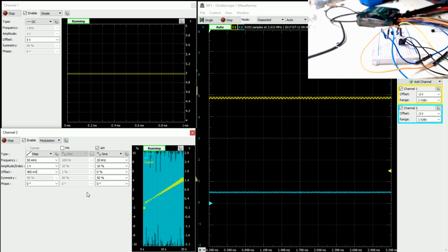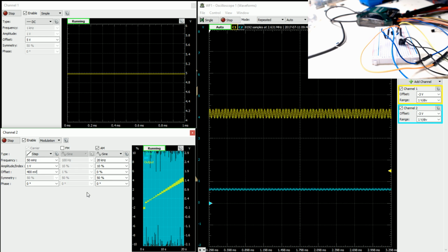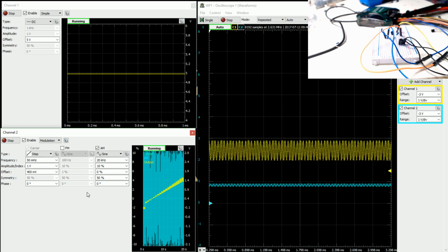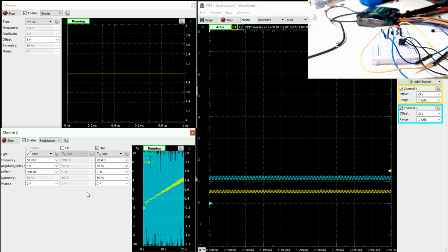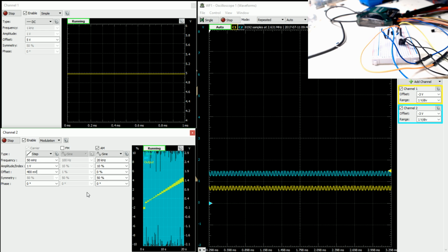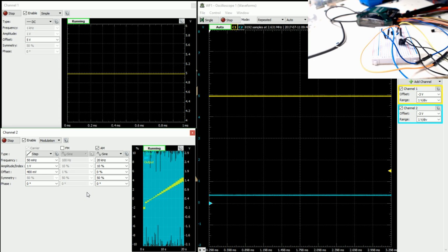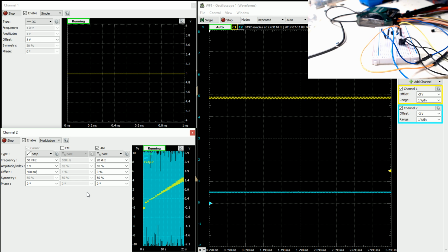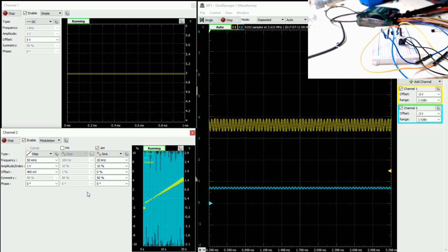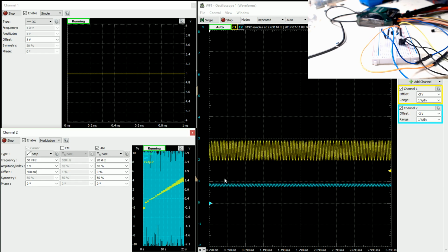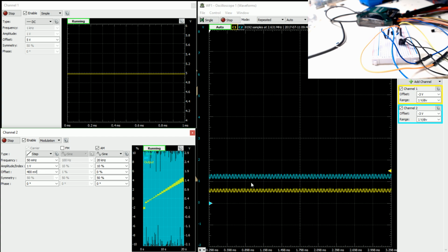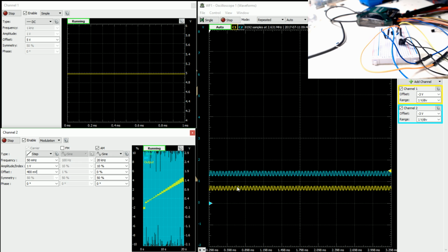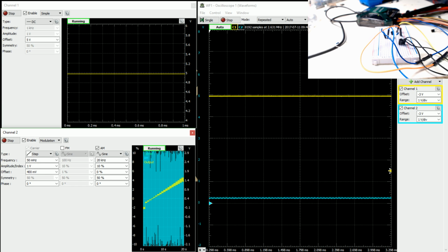I have to go through one more cycle here. Because if it goes past the 1 volt mark, what we'll start doing is basically running into the territory. Is it still moving? No, it's not going past there. That's weird. Let's try this one more time. If it does get past the 1 volt mark now, what we'll see is that it's going to start overloading basically. So this represents about the max amplification here. Yeah, okay, it is doing that. It's just the triggering's off.